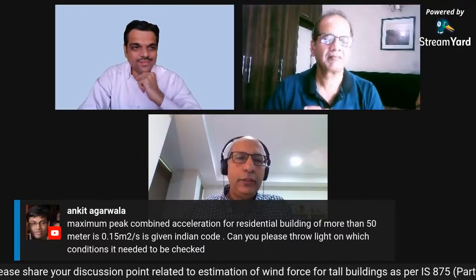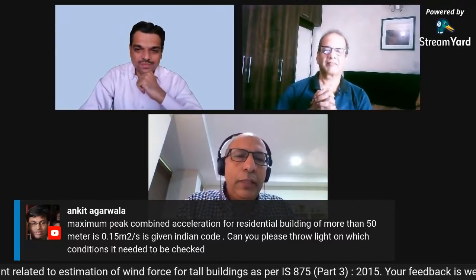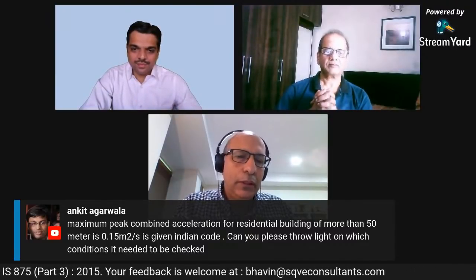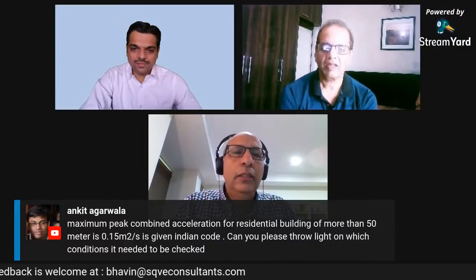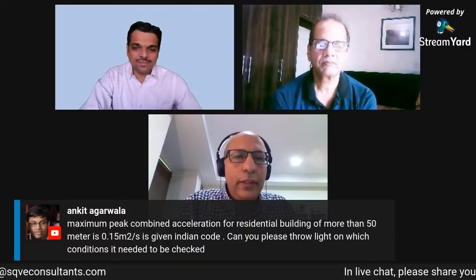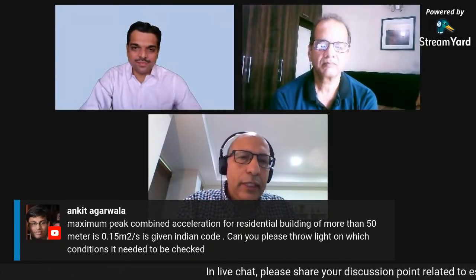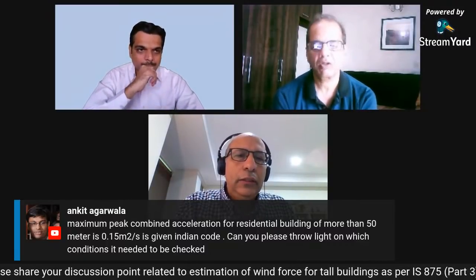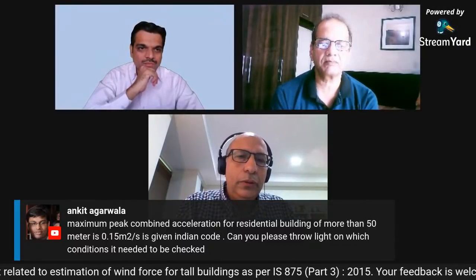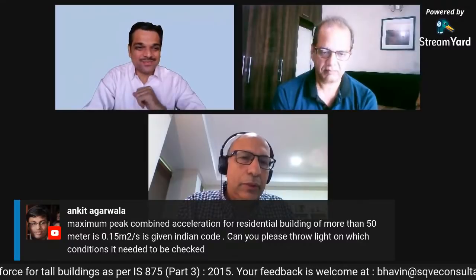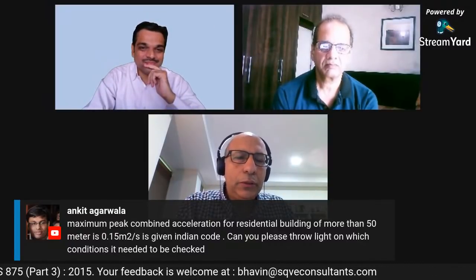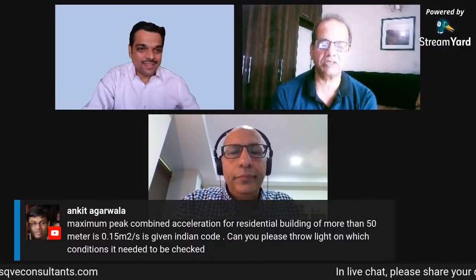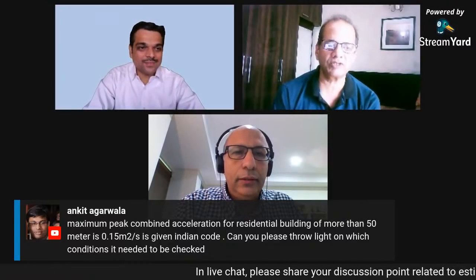Obviously, every person is different, but these studies are based on many thousands of subjects, and interviews with many people in Hong Kong, where there are many tall buildings, and so it's been established that there is a very clear relationship between perception of motion and the natural frequency. So I encourage you to use these guidelines in the Indian standard, but also use what's in the ISO standard. Okay, I will have to leave the meeting at this point, and you may continue with the questions.